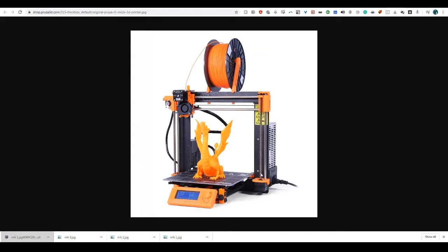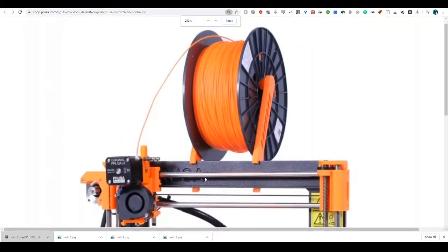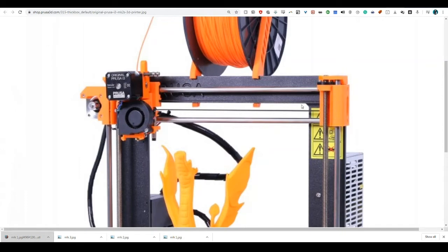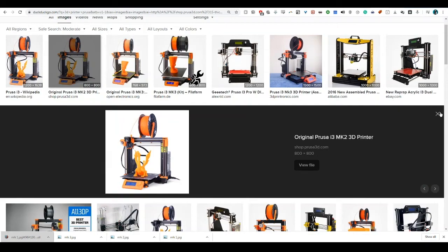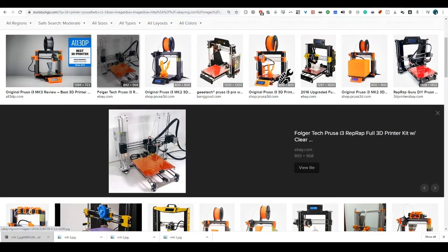They're all the same accuracy. Now, the tightness of these machined threads or spirals on these rods do affect the accuracy or the precision. And if you look closely, if you can see them, the belt that controls the motion in the X and the Y is one underneath here. Those belts have a resolution associated with them. This one shows it pretty well.